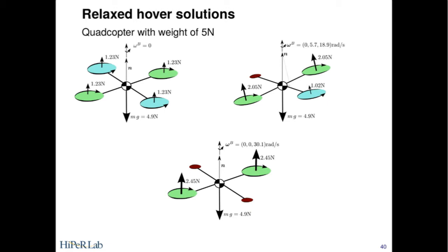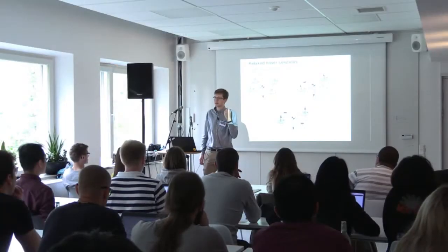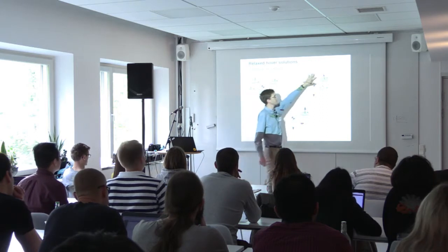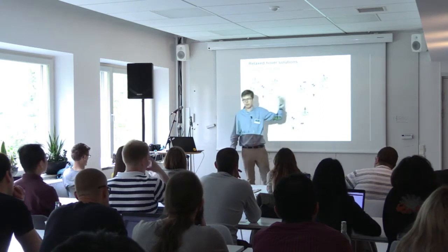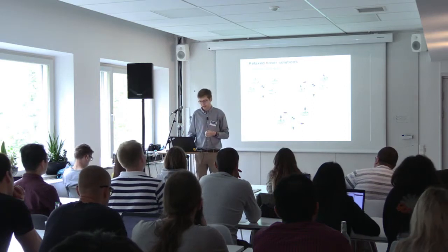So what this suggests is that I can find a condition for the system such that if the system is in that condition, it will stay there, right? So if I have a multicopter with a failed motor and I can bring it to this angular velocity with these forces, it will be able to maintain an average position in space.